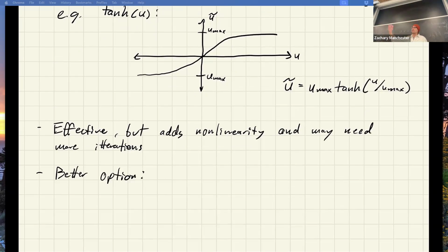so remember, we're doing this backward pass and we're solving this min over U at each step in the backward pass. And what we did before was just take a gradient with respect to U, set it equal to 0, blah, blah, blah. But you don't have to do that. Remember when we did dynamic programming and Pontryagin and all this stuff, we made a whole point about how when you solve that min over u problem at each time step going backwards, you can just enforce the control limits explicitly there, right?